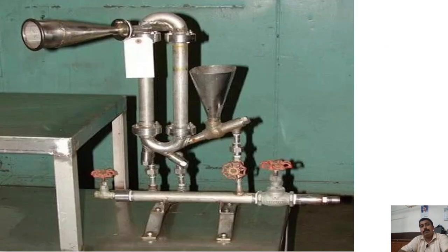Next, we'll see this general image of the fluid energy mill. I have intentionally included this image because based on the image you can better understand how the fluid energy mill looks. You can see here the hollow elliptical loop which is made up of stainless steel. This is the feed inlet, and this is where the gas is introduced, from the hollow pipe. Here you can see the nozzles to adjust the velocity. So powder material breaks within the hollow loop.